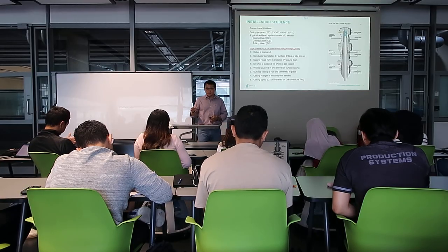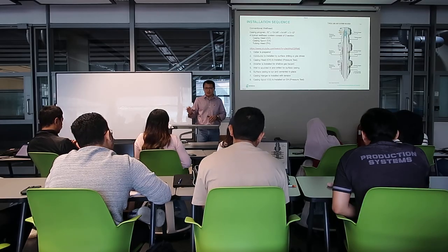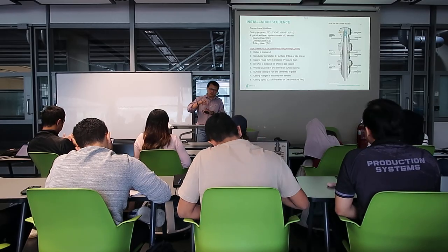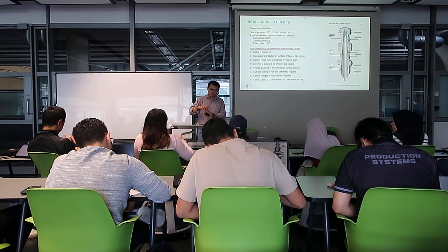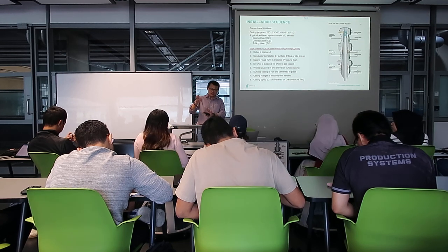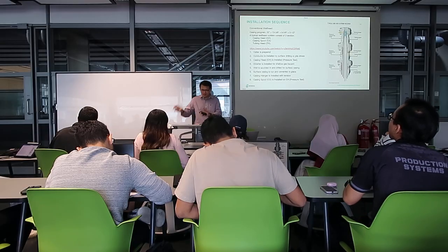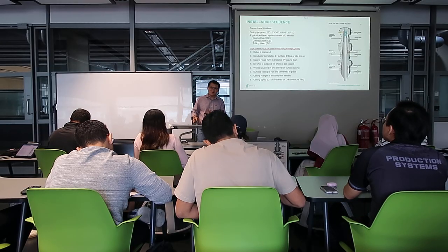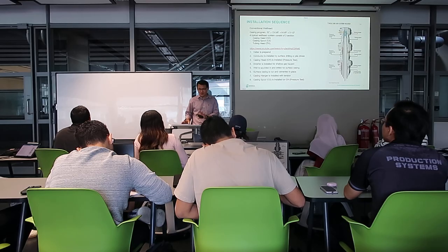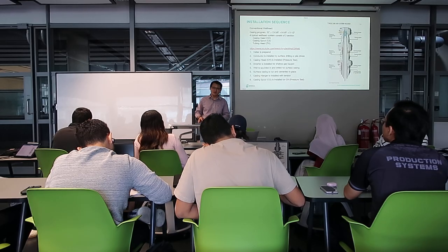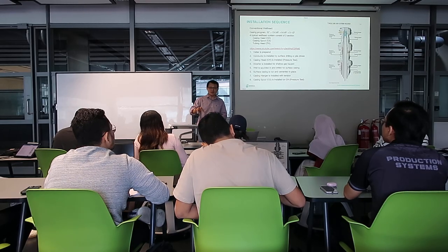So BOP test is one thing. If we put the BOP on top of the head, then we will do the test now. But if at that time I need to take down this BOP, then there are NPT hours incurred, which we try to avoid. Those days it was quite a standard practice.